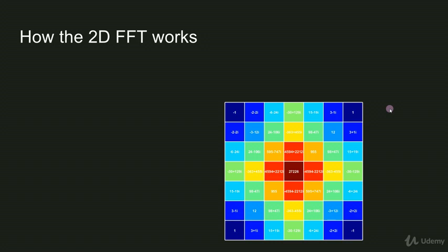What's tricky is figuring out how to map the features of an image onto locations in the 2D Fourier plane. And you know, when people teach the 2D Fourier transform, they typically jump immediately straight into showing power spectra of natural images. But I think it's better to start with really simple images and first to try to build a bit of intuition about how to interpret the 2D Fourier plane. Therefore, what I'm going to do in the rest of this video is show examples of how spatial frequency, phase, and location affect the 2D Fourier transform.